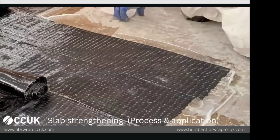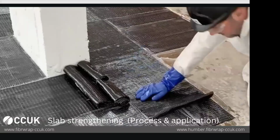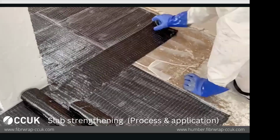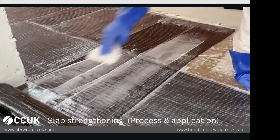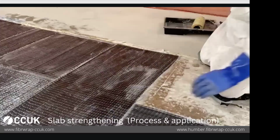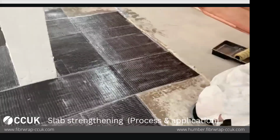But you'll also note here that the carbon fiber which this guy is applying is actually in wet condition. So it was saturated in a different area on the same site. So when he's applying, it's in the wet condition, and that's why it is called the wet layup method. And that is the correct way to do the FRP application.